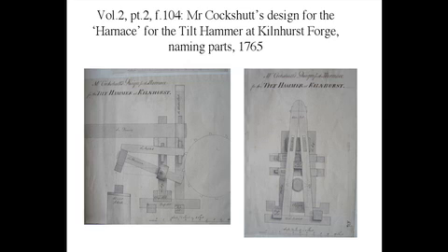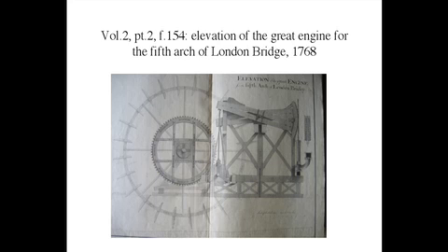The most famous and by far the largest water wheel erected by Smeaton was that for driving the pump on London Bridge, under the fifth arch in from the Surrey shore, which he made for the committee of the London Bridge Waterworks. This was huge. It was 32 feet in diameter, with 24 flat floats, which were 4'6" deep, driving forcing pumps through wooden gears.